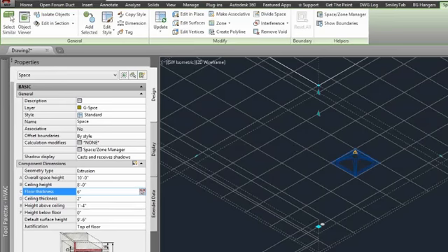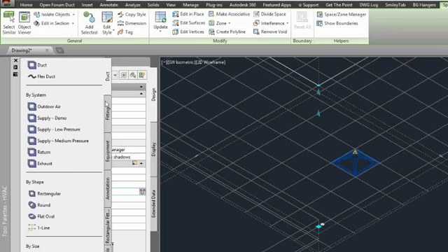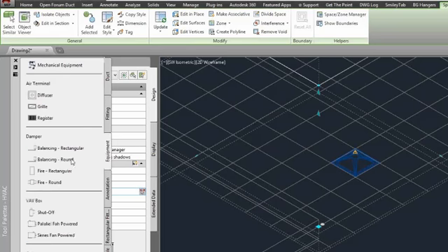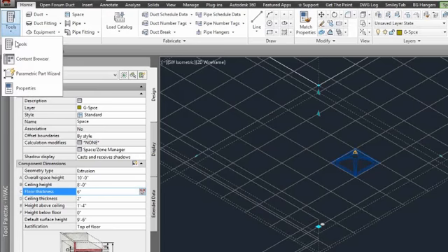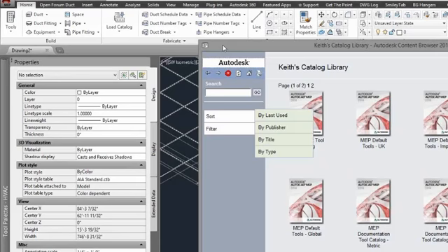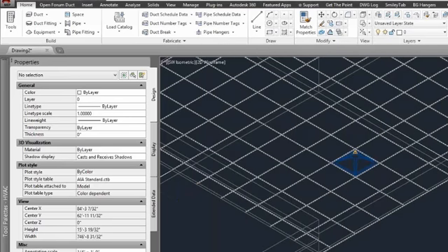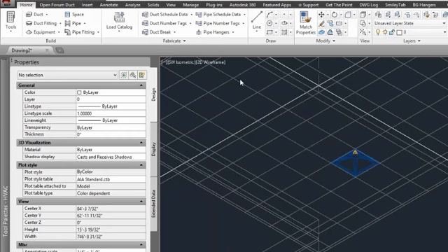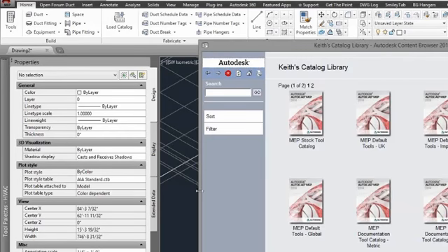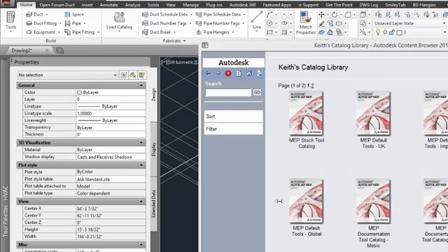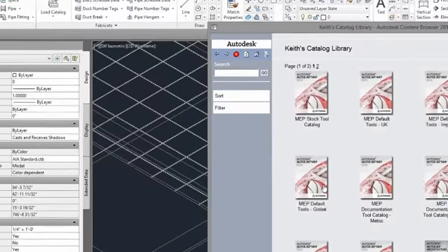First, let's go ahead and get our tool from our stock tool catalog and drag it onto our tool palette. Now I'm going to go ahead and bring it on into my equipment tool palette right up under my mechanical equipment. So our tool palettes are located in our content browser, which is on the home ribbon. I select content browser. It pops it up. I like to go to the top bar and go ahead and select always on top. That way when I select AutoCAD like I did there, you can see that that dialog goes away. But if I have that selected, when I select AutoCAD, that dialog does not go away. It's useful for dragging and dropping items to and from your tool catalog.